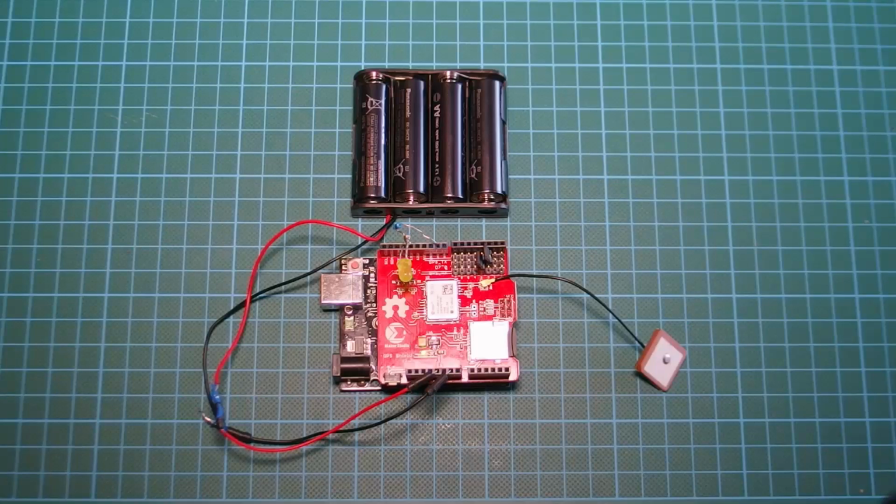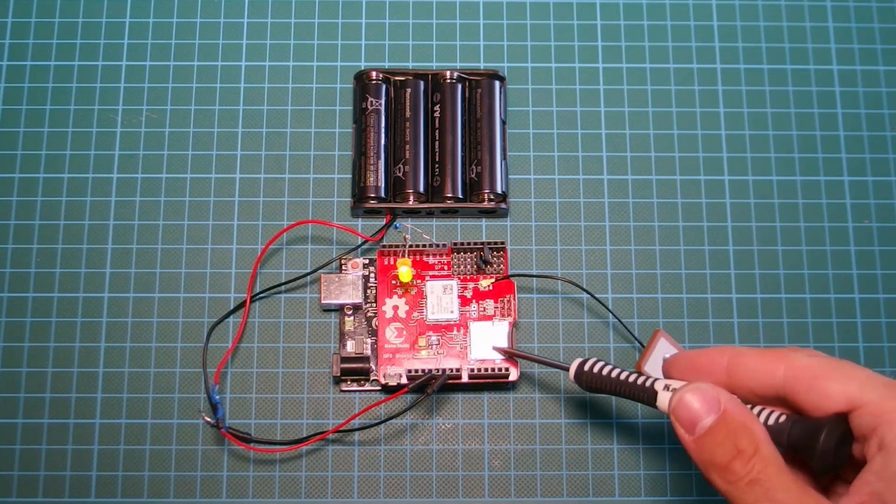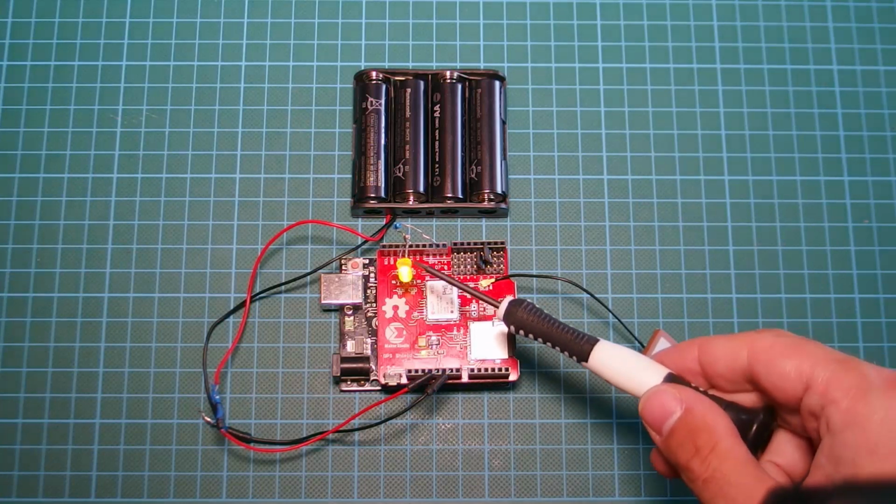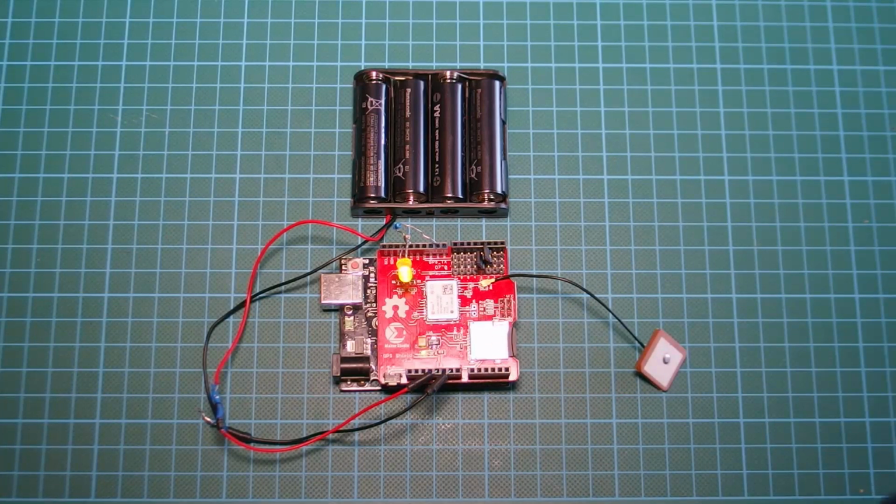Let's start. In today's video we are using the GPS shield from Maker Studio in order to store our location's coordinates in an SD card. We read our location's coordinates every 5 seconds along with date and time. All this data is then stored in a comma-separated file in a micro SD card using the shield's embedded SD card module. For convenience, I have also put an LED on the GPS shield in order to visually check the status of the program that Arduino is running.